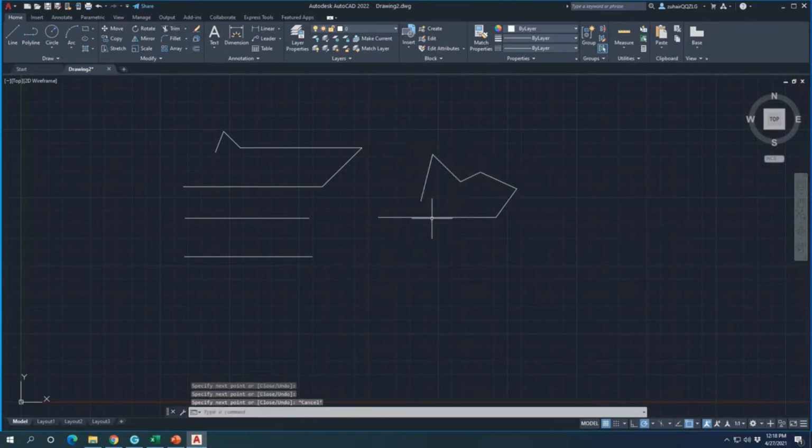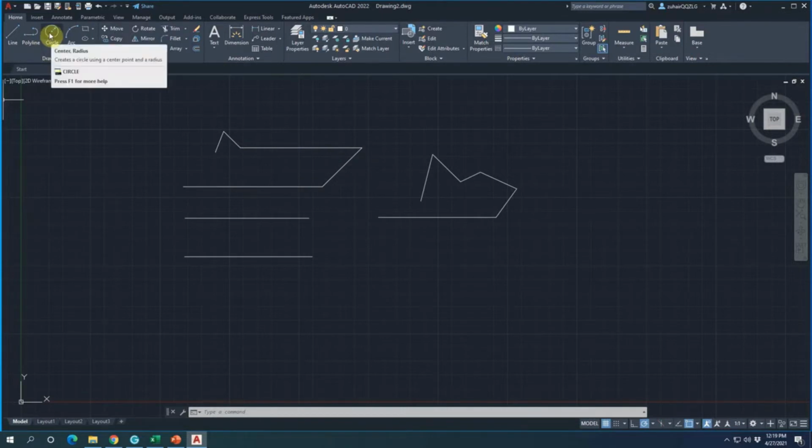Like this. If I choose this line, the other line will not be selected. So if I use line, the lines are separated, but if I use polyline, all the lines are connected. Okay, so this is the difference between using line and polyline. Sometimes it's better to use line, and sometimes if you want to draw something that has some interconnection, maybe the polyline is more suitable. And then let's just draw circle.